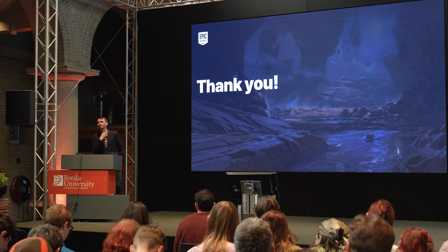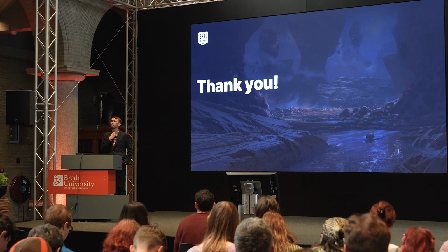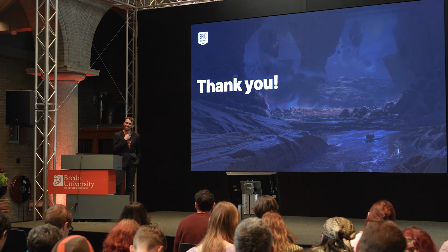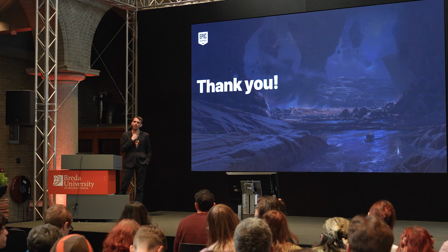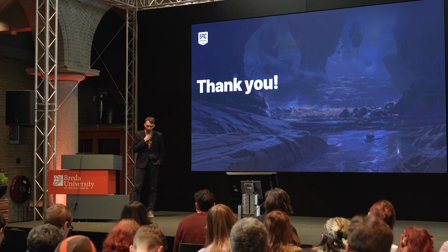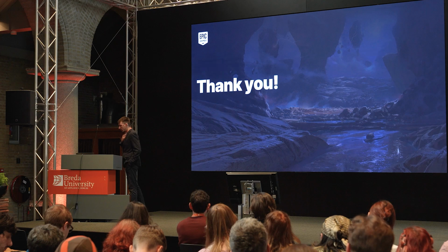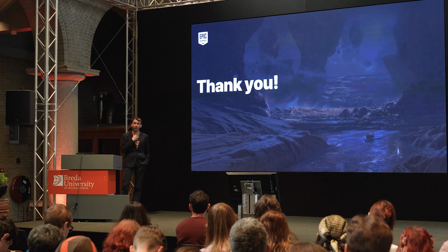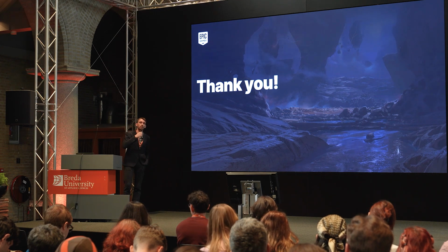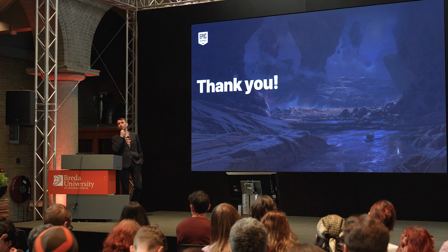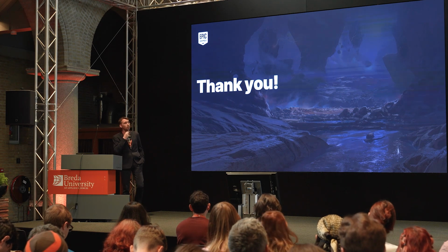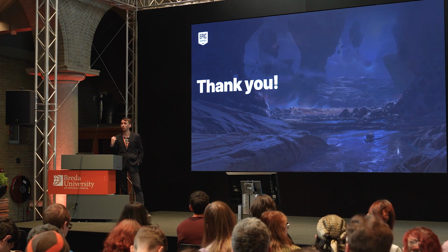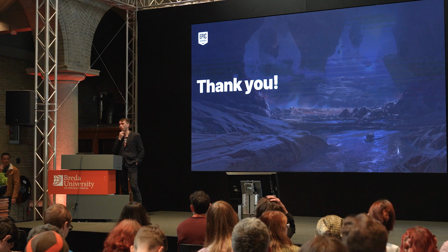Okay, and for vertex color and custom primitive data, can you pass that through PCG? Okay, so yeah, you can. We have support for custom instance data per instance on the ISM, the instanced static mesh component. Unfortunately, we don't have custom primitive data per component right now, so you need to push it to every instance. But we plan to have support also for custom instance data. And for vertex color, I don't think we can push it right now directly, but you can read from it with the mesh sampler. You can read the vertex color.